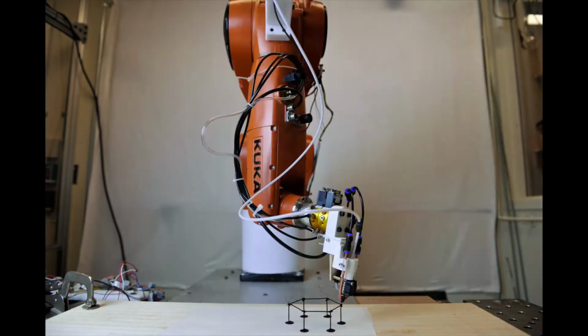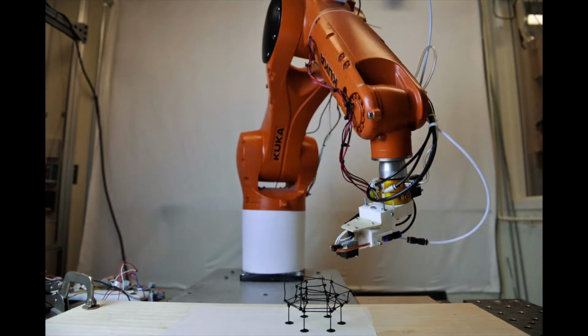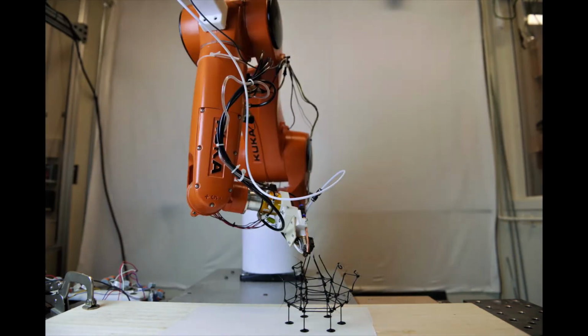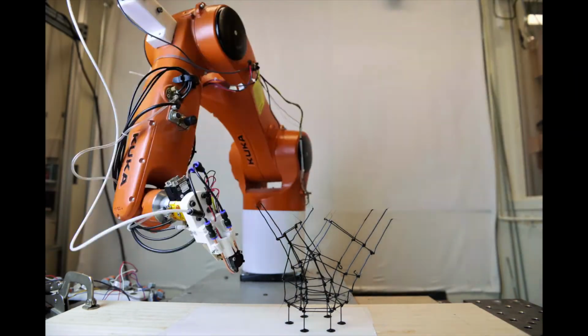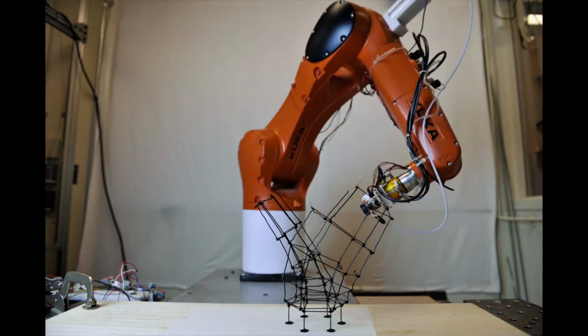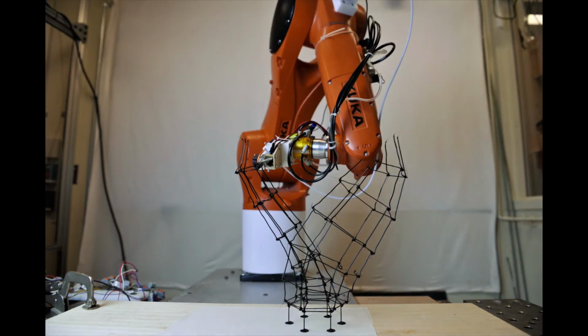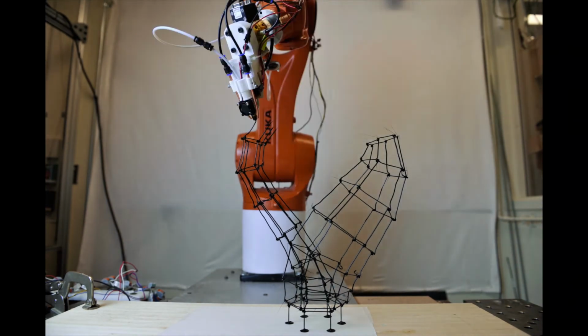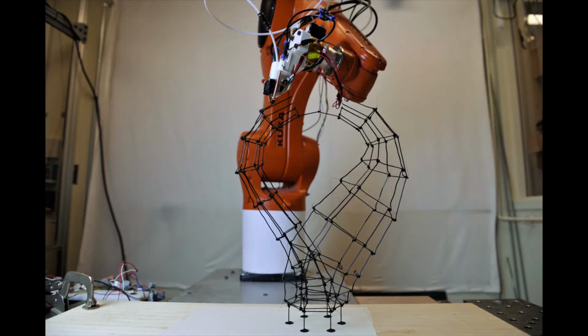Here's an example of a real-world robot printing the Klein bottle. The robot is a KUKA arm outfitted with a custom end effector that is able to extrude plastic line segments in 3D space. Printing the Klein bottle is particularly difficult because the elements overlap quite a bit. Also, there isn't an obvious ordering of elements to a human that will enable the robot to successfully perform the full sequence of extrusions. However, using our algorithms, we were able to successfully plan to print this structure, which has around 250 elements in only 10 minutes.